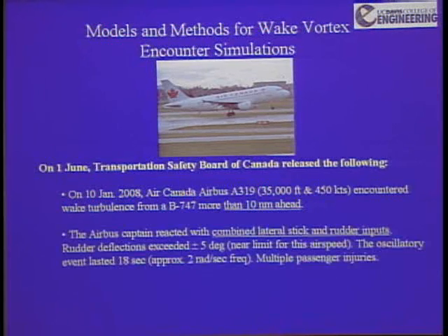Well, what happened? The Airbus captain reacted with combined lateral stick and rudder inputs. Bad. The rudder deflections exceeded plus or minus 5 degrees. Doesn't sound like much, but that's the rudder limit at that airspeed. The oscillatory event lasted 18 seconds. The frequency was about 2 radians per second. There were multiple passenger injuries, people getting thrown all around the cabin.